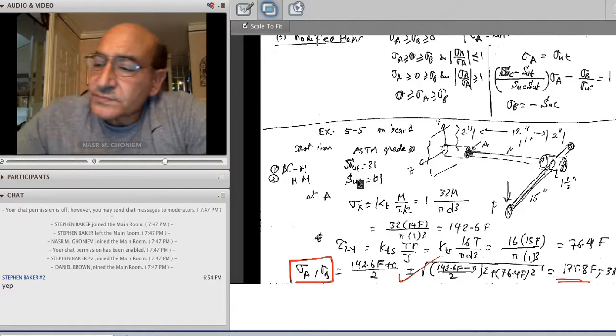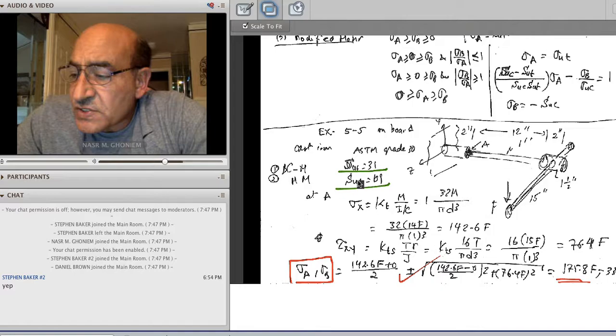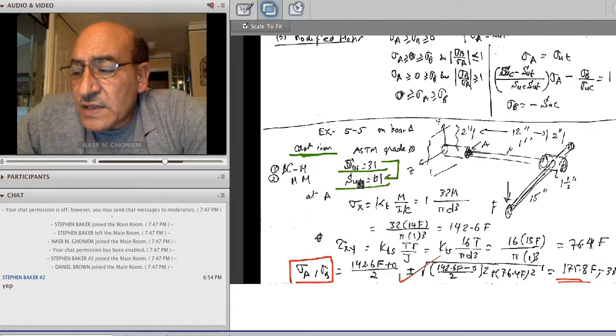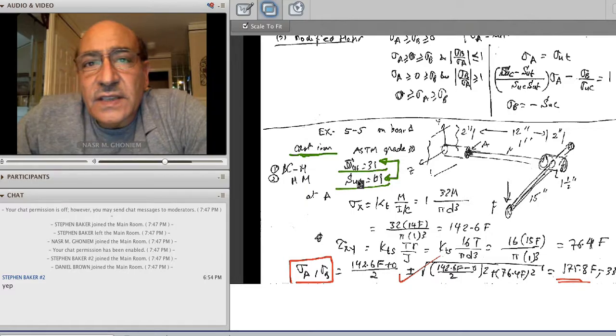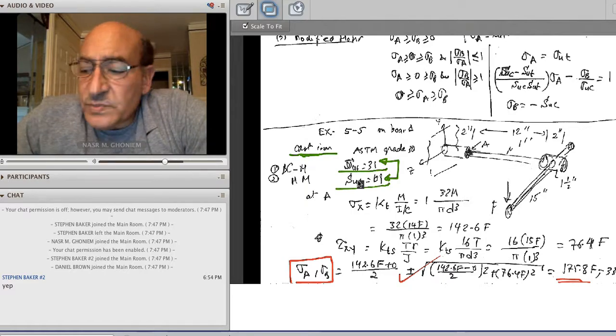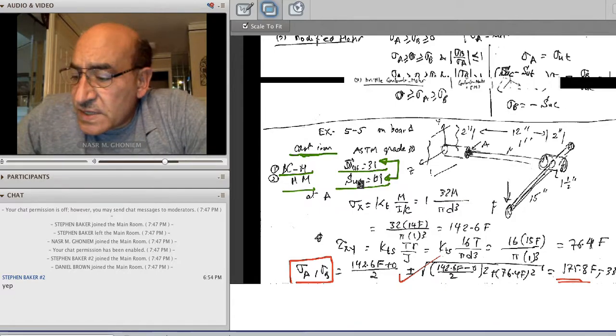Once we know the material properties, we know the ultimate in tension and the ultimate in compression, and then since they told us it's cast iron, then it triggers in my mind that it is going to be a brittle material, and therefore it's corroborated with the evidence that the ultimate in tension is much smaller than the ultimate in compression. So I immediately have to go to brittle Coulomb Mohr or modified Mohr. So I can just assess both cases here. So that's what we did.